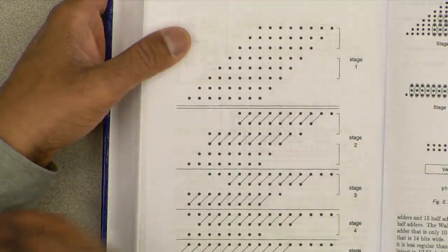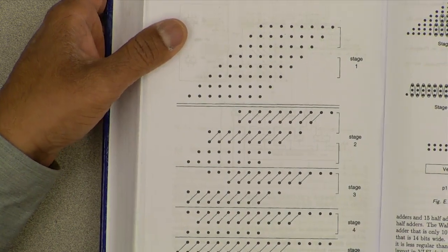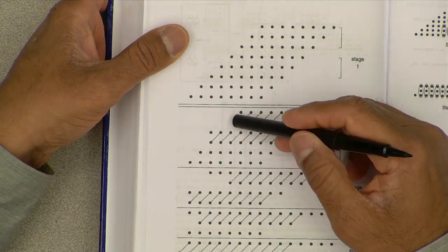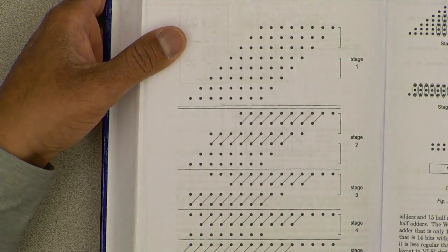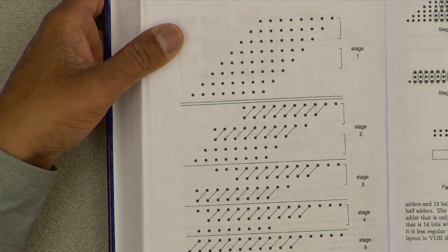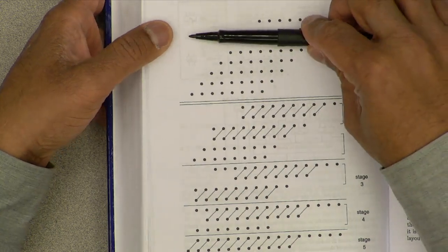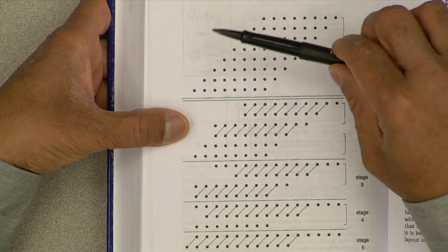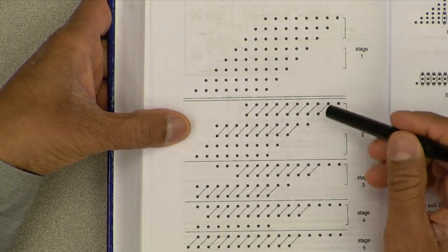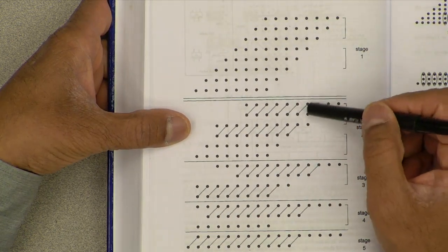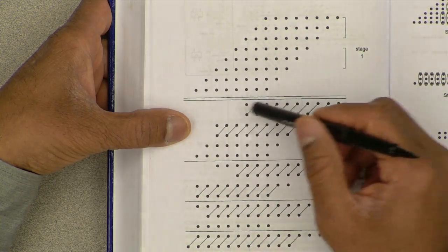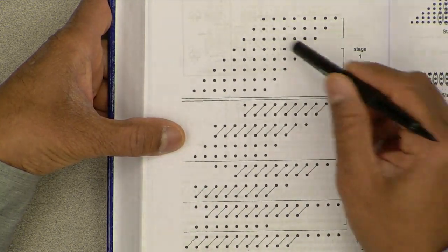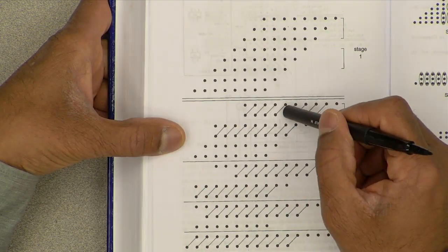What happens if it is 8 by 8? Now we have 8 rows to add. We don't need to convert these to triangles. So here is how that works. Take the first 3 rows, and replace the first 3 rows at each position by a sum and a carry like that. So 3 lines create 2 lines.